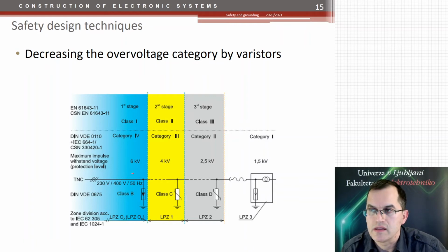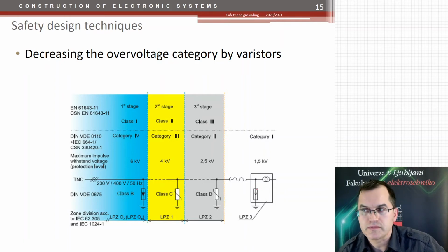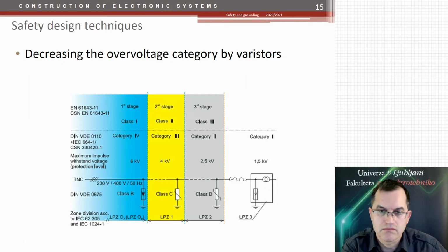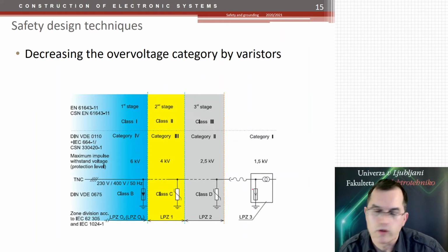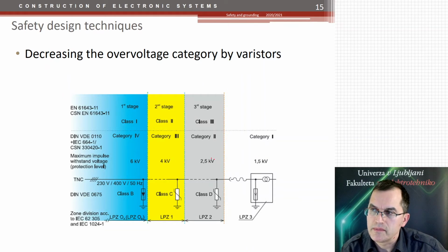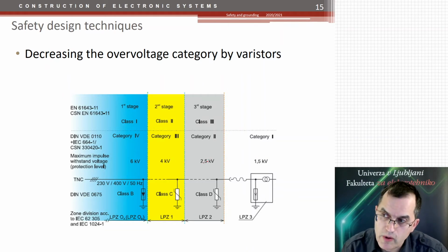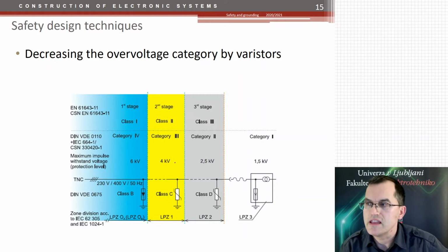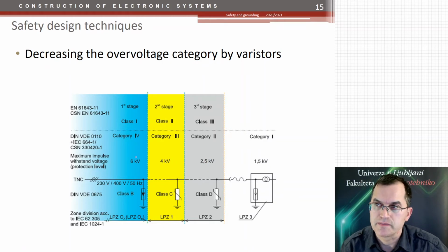And this is the overvoltage category classes shown in terms of the high voltage suppression circuits, such as suppressors used in the mains distribution network outside your house or inside your house, or in the sockets, or even in your low voltage devices. So these are the maximum impulses that are expected to happen in the worst case in different category levels.